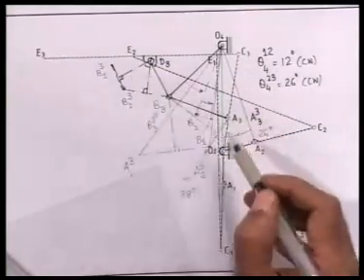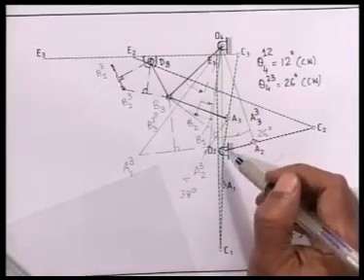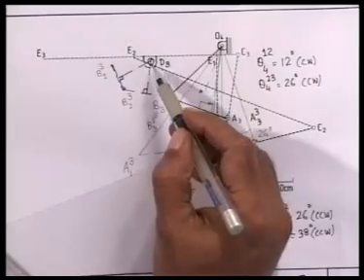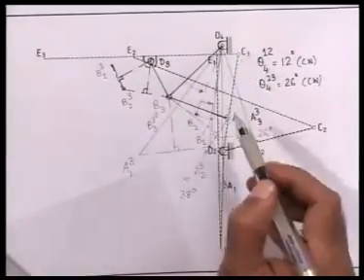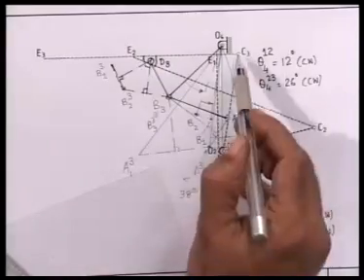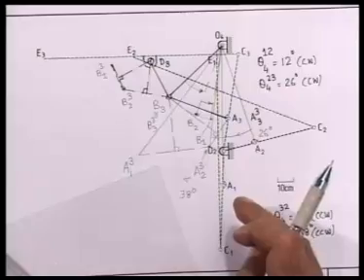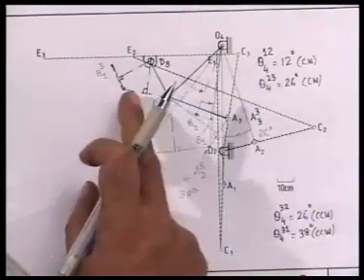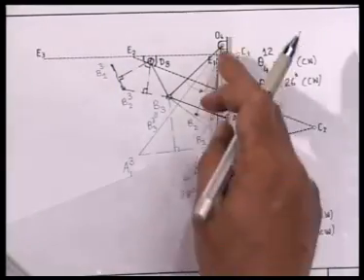This completes the design of the 6-link mechanism for the door board, namely O2, A3, B3, O4, D3 and C3, E3, corresponding to the open configuration when the door board is parallel to the roof of the garage. By driving this mechanism, I am ensured that the door board will go from C3, E3 to C2, E2 and then to the closed position C1, E1.